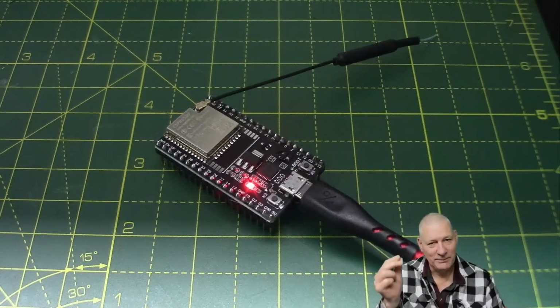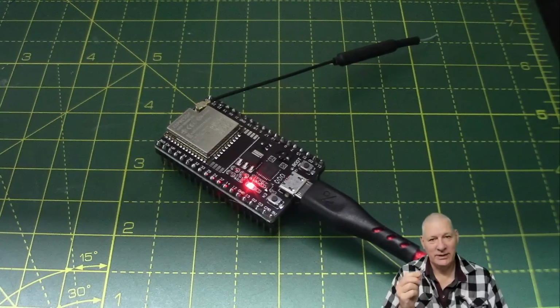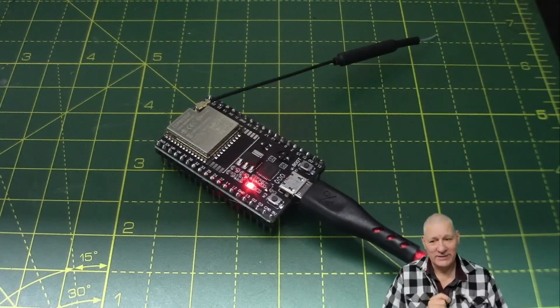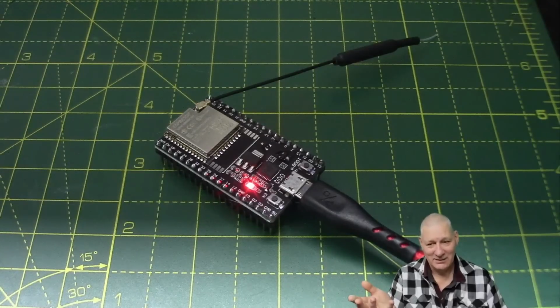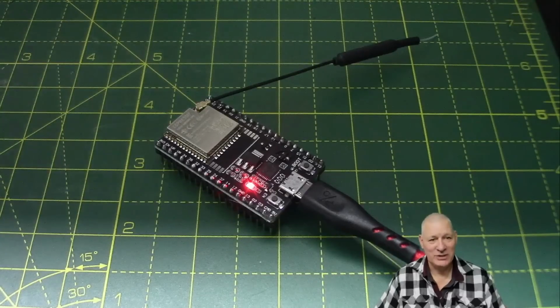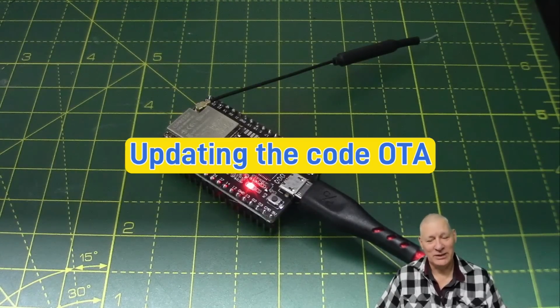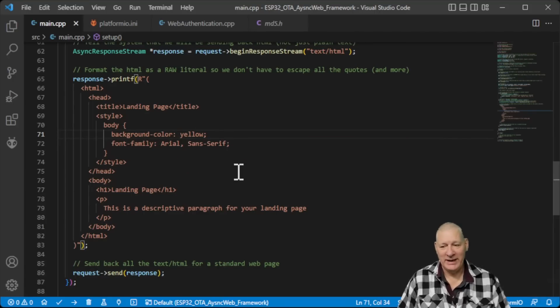Now, I said at the beginning of this video somewhere that by using the ESPAsyncOTA library, it gives us a free way of updating code on that device without going through the USB cord. Now, you're going to have to take my word for this, because I've got to keep the USB cord connected just to keep it powered up, but we're not going to use that to upload the code. Let's have a demo, shall we, of how we can do that. So in the code here, it says the background color of the page is yellow.